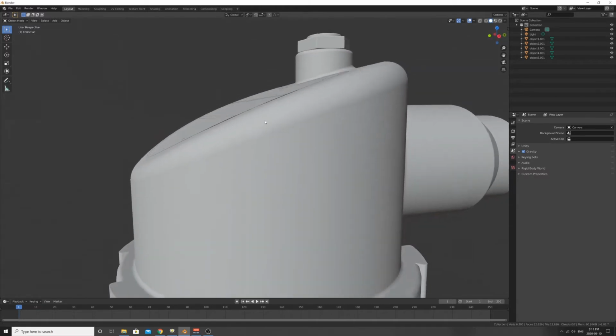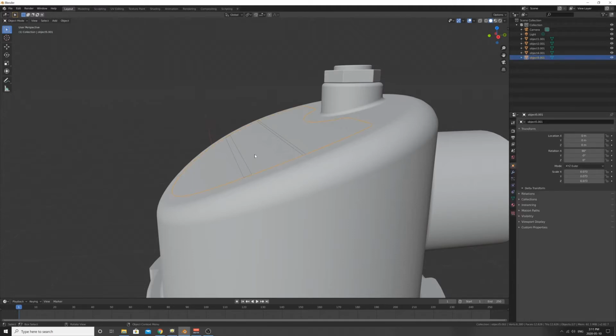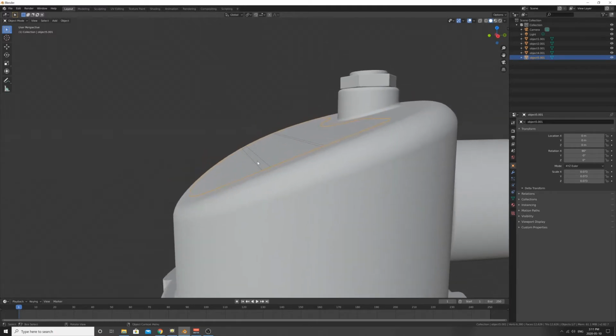And you notice that there are these little tiny lines in my case, and this is just to illustrate what can happen to you, and how you can get out of these situations. These lines indicate that the decal surface is intersecting with the body, and we don't want that. We want to make sure that this surface is just proud of the body, standing offset just a little bit. So if you select this decal surface and press the G key and move around, you can see that it moves in screen space by default in Blender. After you've pressed G, you need to press the Z key to move up and down. So you can move it so it's offset just a little bit. I've still got some left over, so I'm going to press G and Z again.